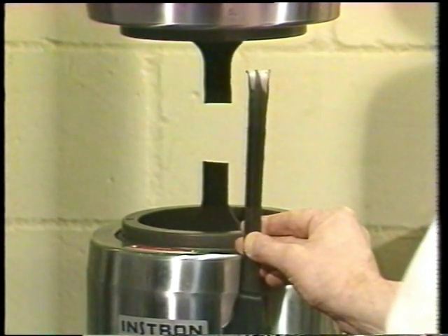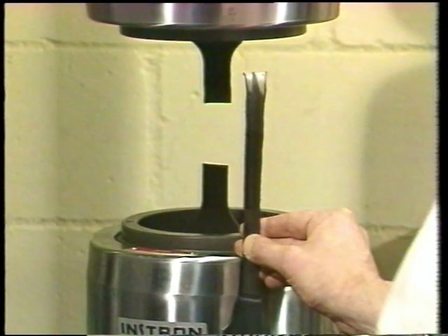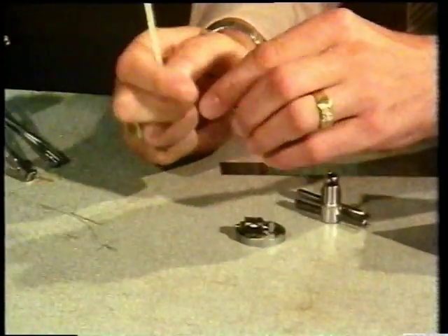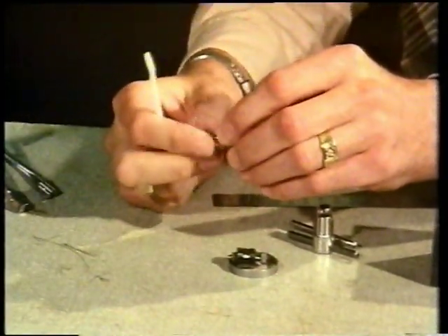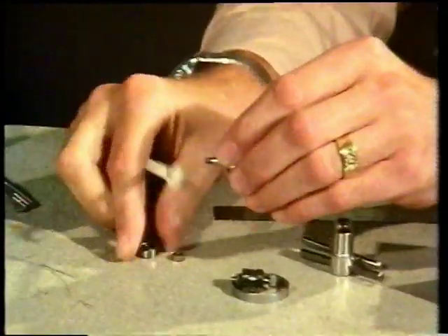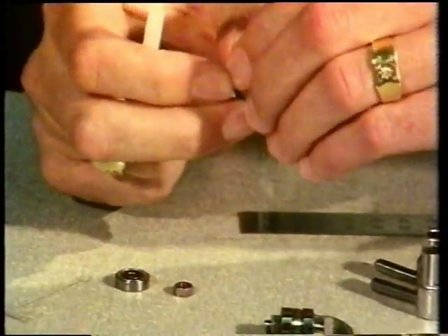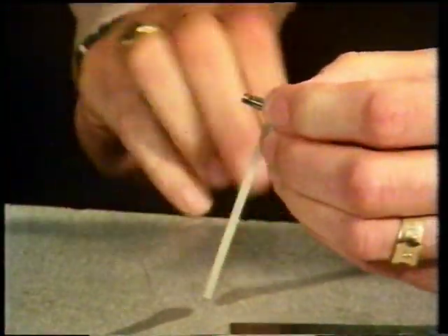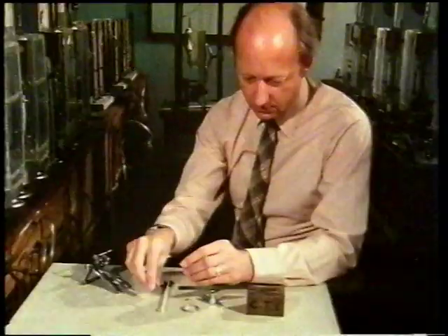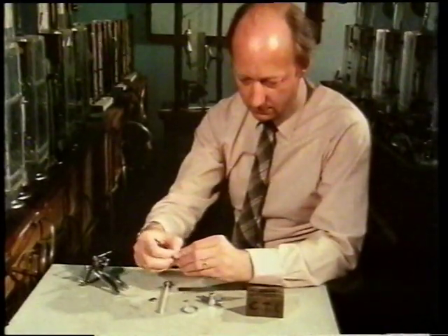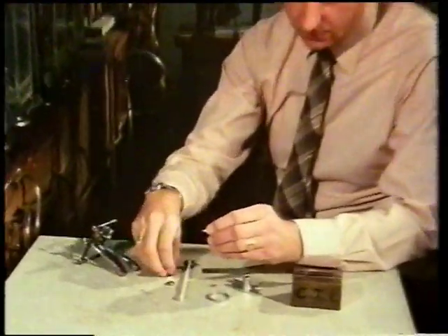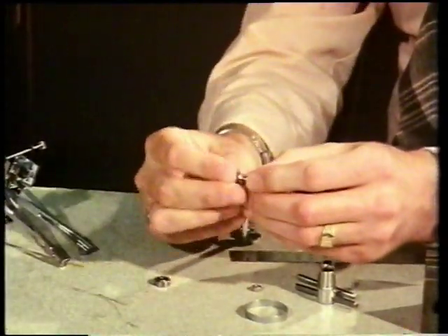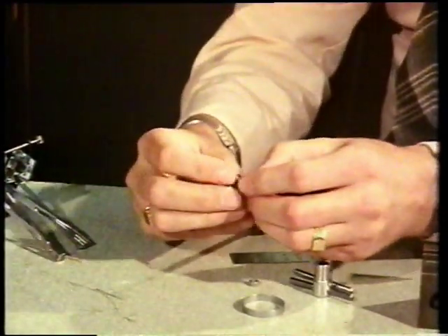What happens to plastics if we go to even longer timescales? Here's a specimen being prepared at an industrial laboratory for a different kind of tensile test, a tensile creep test. Here we see the extensometer being fitted. The specimen will be put under constant load and its increasing extension with time recorded. Because these tests are long-term, lasting a year and more, and are then used to extrapolate to even longer times, a high degree of accuracy is required.